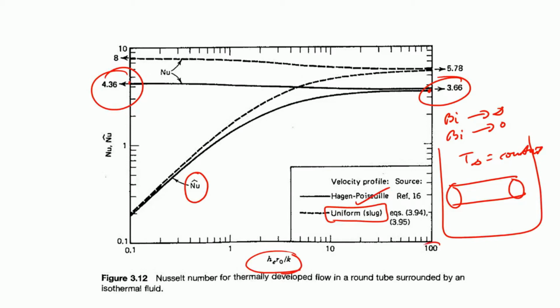As you can see, a Biot number of 100 is very high, that is, it mimics the Biot number approaching infinity, and 0.1 is a low enough Biot number that you can take it to be a very low value. So, based on these two things you have the two limits that we established in the last class, where we showed how the duct side Nusselt number should vary.